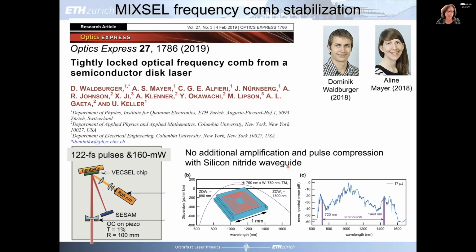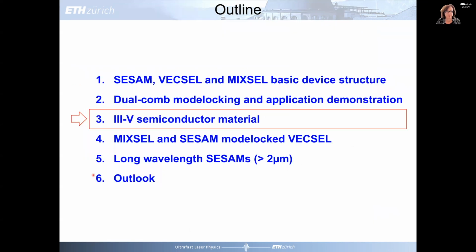And that is something, when you actually use a semiconductor, when we wrote our proposal, people argued that this is not possible because the mode-locked semiconductor laser will not be low noise enough. But this is basically to emphasize that, again, this is because we have a high-Q cavity, because we go vertical to the quantum well in the gain.